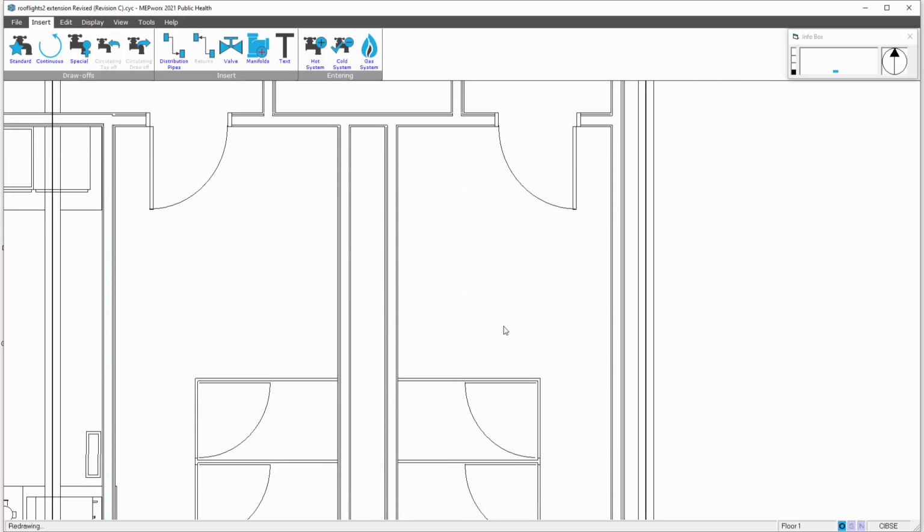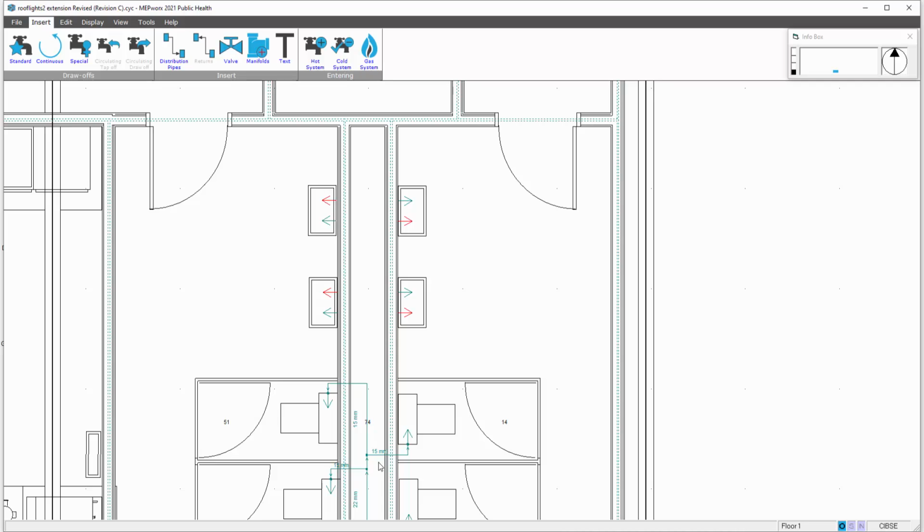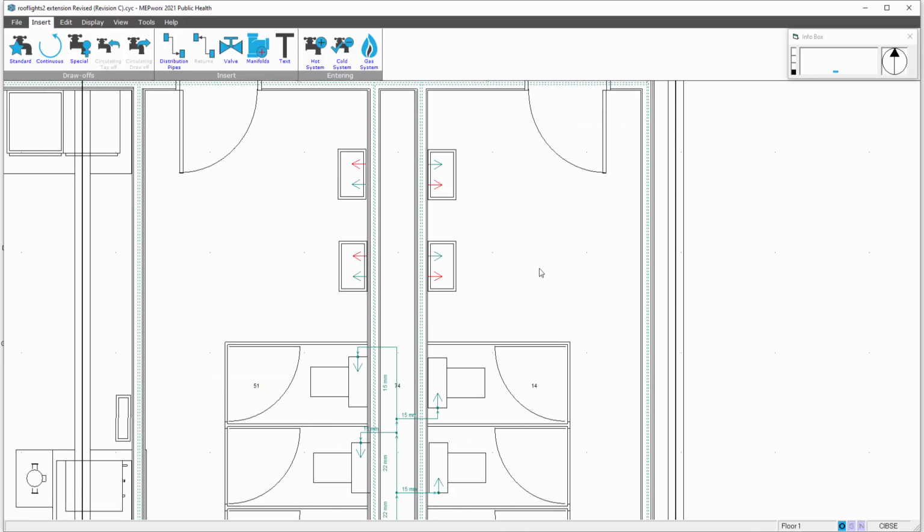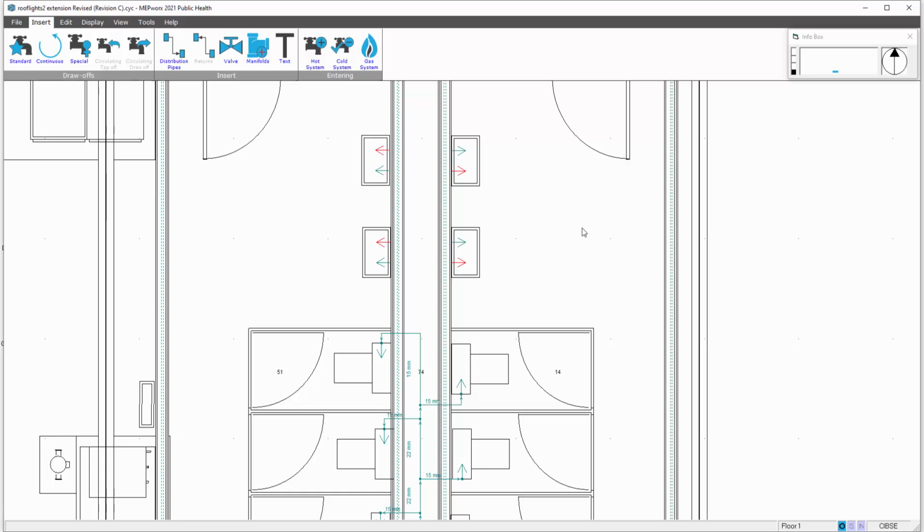So as I've done here, I've done my tank fed system first, use the auto connect to connect the pipes, then doing my separate system. So first let's look at a mains cold water system. It's the same approach, except on the entry point we apply the main supply pressure. So this could be part of a boosted set or the supply into the building.